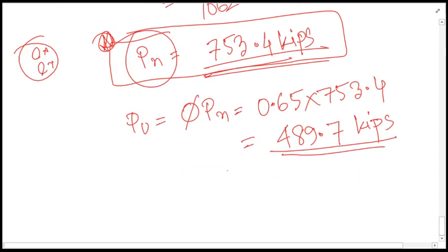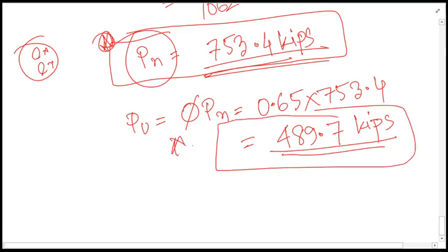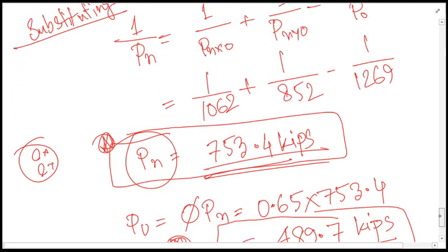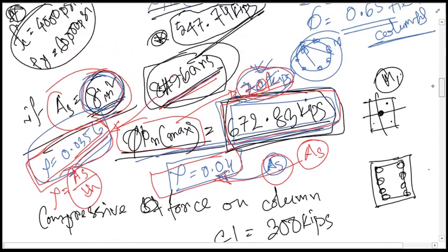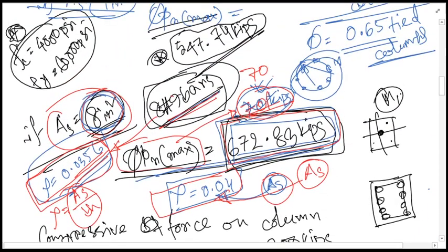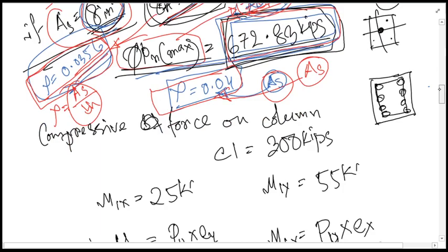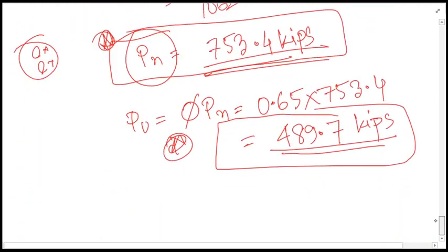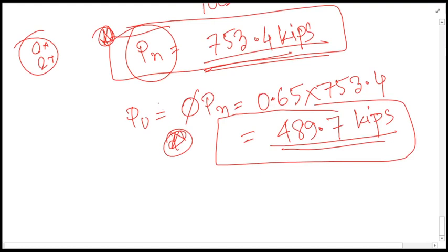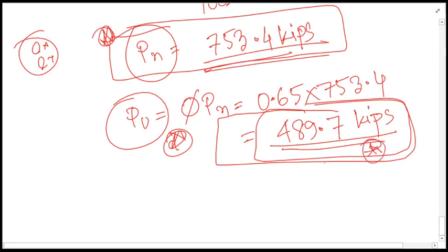This is the reduced capacity of the column, whereas if it were the concentrated column, then the nominal capacity would have been 701.70 kip. It might take that if it is concentrated without any eccentricity or bending moments, but whenever it has bending moments acting over there, then the reduced capacity is this one. Up to this axial load it can